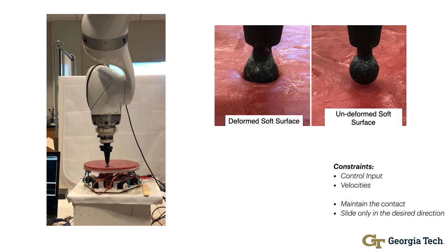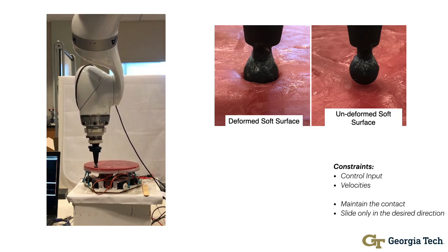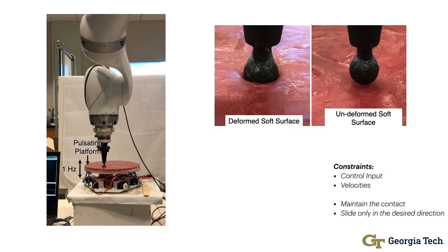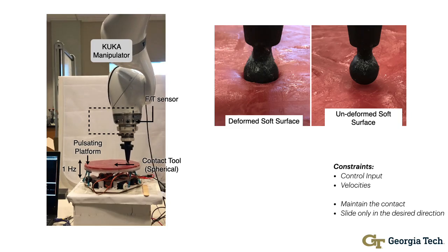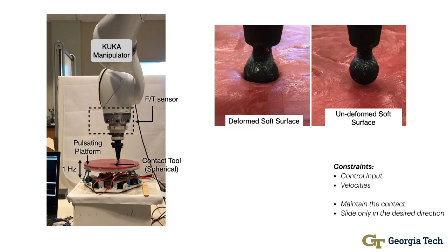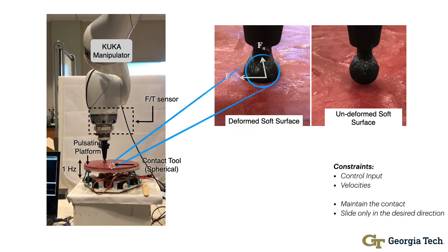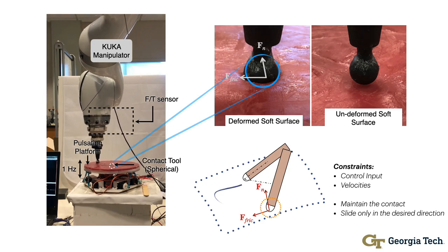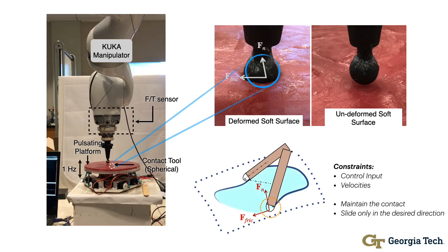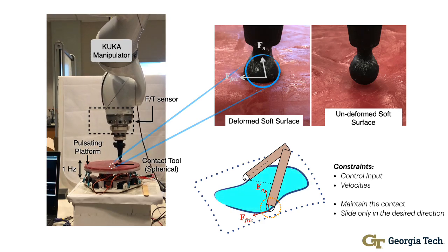In this work, we explore the possibility of using soft contact in trajectory optimization. Our setup includes a platform with a soft substrate and a manipulator with a force sensor to perform motion and force simultaneously. On a force-controlled, low-impedance robot, force and motion are coupled since frictional forces could affect the motion and vice versa. To achieve better force and motion accuracy, we use a contact-aware distributed optimization framework.